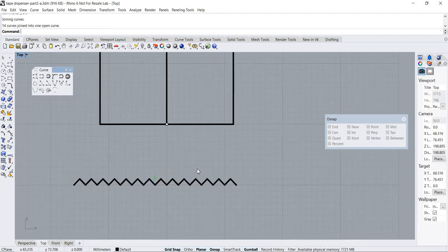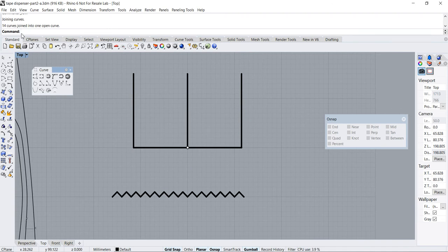To do that, we can use the Orient command. If you want to have a better understanding of the process of scaling this to here, you might want to click on this label here to go to a more in-depth tutorial about this method of scaling objects to fit onto two specific locations.